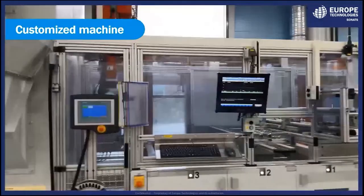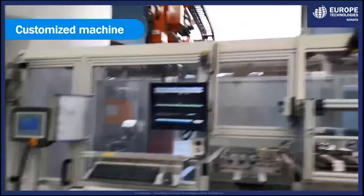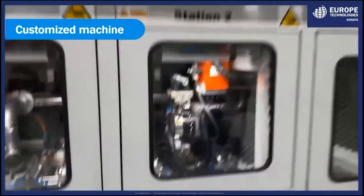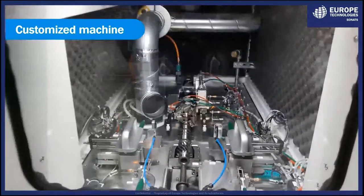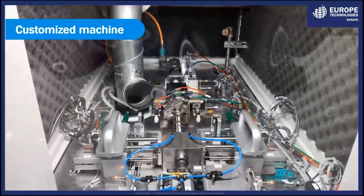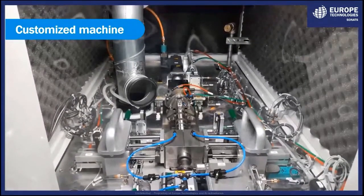So as already said by Frederic, this operation is done without any masking operation. Indeed, a specific enclosure has been designed and made for each reference. After this operation, the peened part goes outside the machine using the gantry. More often, the peening operation is the final one, and the parts can be stored in a basket or in their final packaging box.